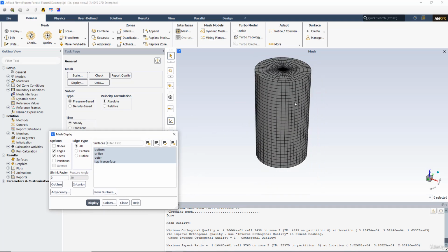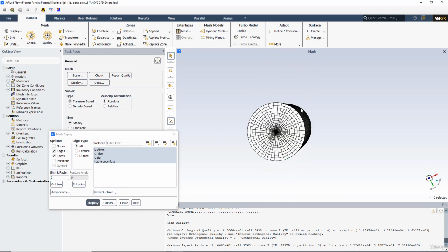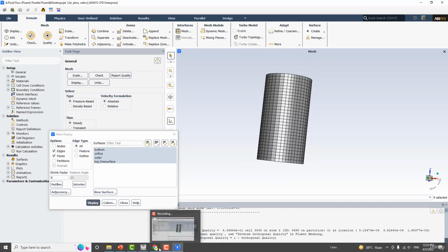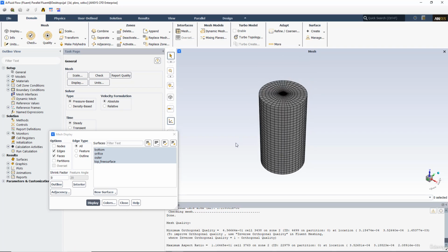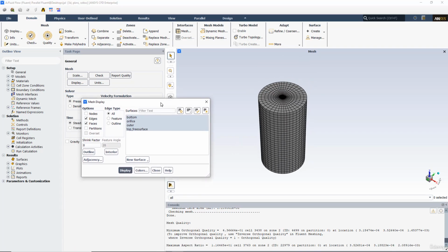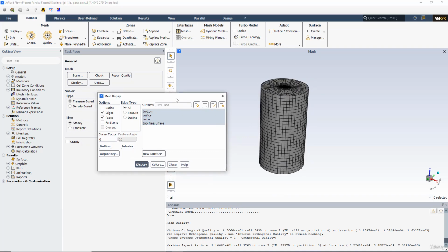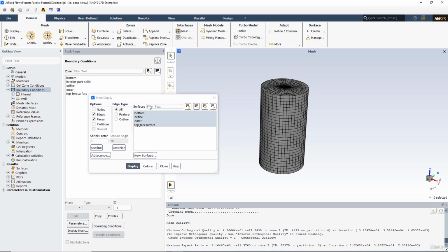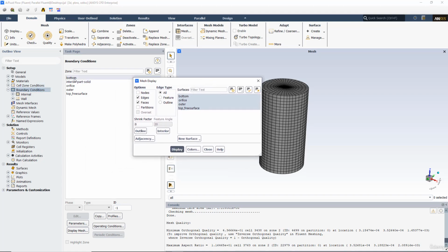Okay, I think that the boundary conditions are not set properly. So if you put the name selection in the proper way, the name types can be decided very, very easily. So if you go to boundary conditions without setting anything at all right now, the bottom side is a wall. The orifice should be the pressure outlet.